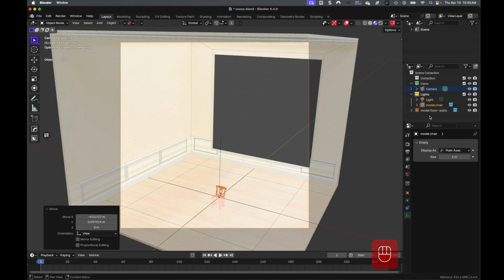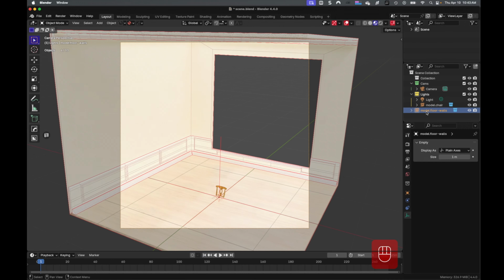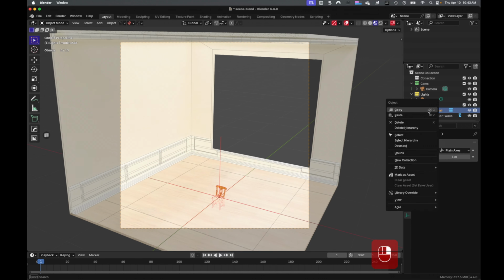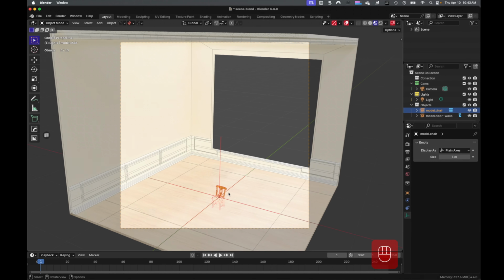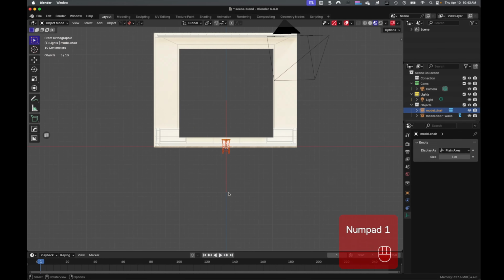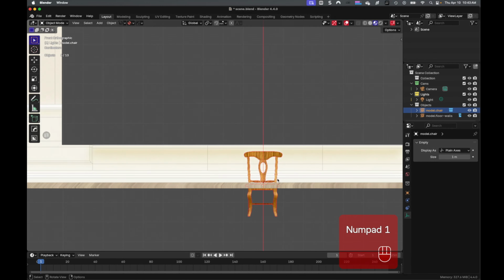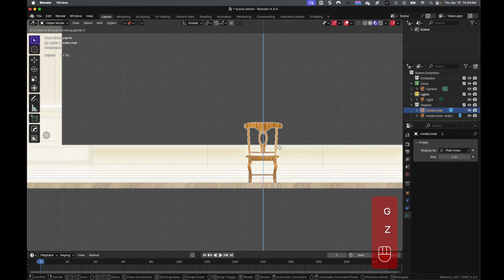And as you see, when we bring it in, it's linked, but it's locked, so I have to right click on the name in the outliner. First of all, let me put it in my object collection. Okay, now I'm going to right click and move everything in the right place. I'm going to right click, go to library override, make selected. So I'm going to override the selection here where I can move it around. I'm not editing the model, because you edit in the original file.